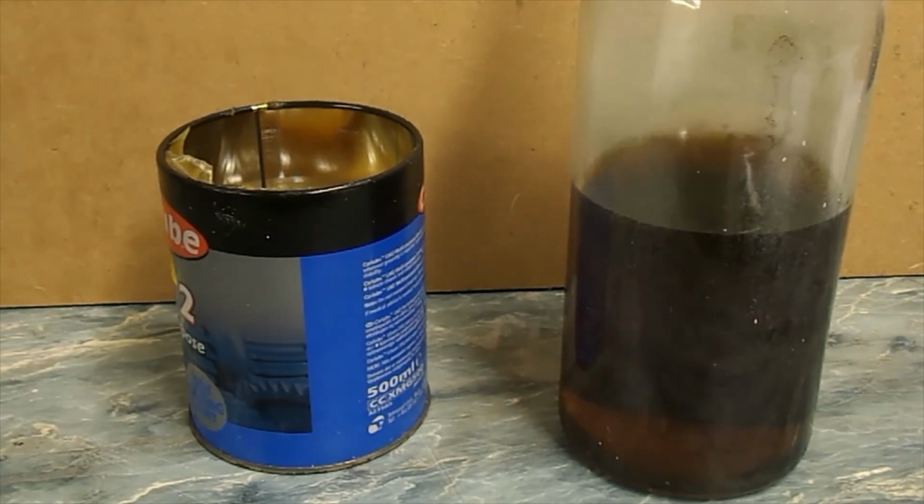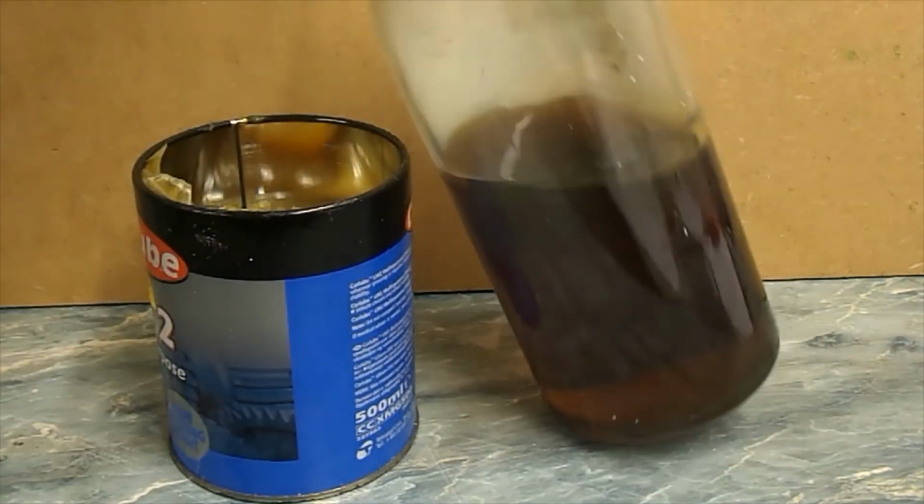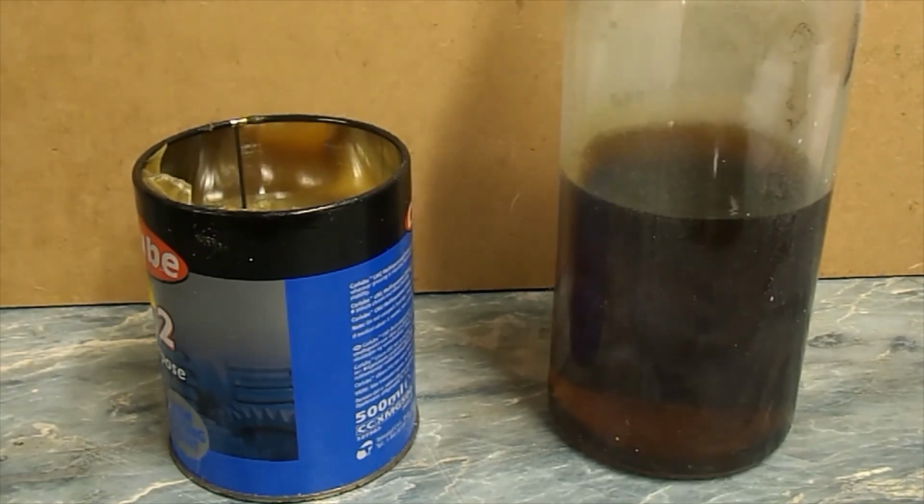There are 2 choices, grease and oil. Generally speaking, grease is the simplest and most efficient choice because it provides all the functions mentioned. But if the bearing is subject to high loads, the operation is continuous and the rotational speed high, then oil is the ideal solution.